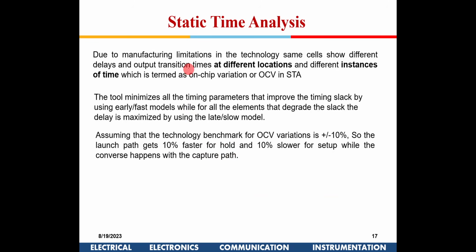Now, when we manufacture flip-flops, when we do VLSI chip fabrication, different locations and different gates can have different delays and different performance. Because the T ox of the MOSFETs involved can change slightly, which can affect the total current capability, or the doping can slightly change.